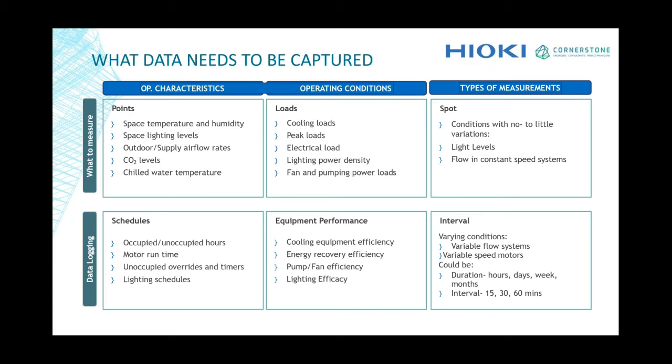When you come to data logging, you have things like when are the schedules of operation, whether it's occupied time, unoccupied times, what are the set points. If you look at motor runtime, how long does it run for, when does it start up, when does it stop, what is the load it's feeding. Unoccupied overrides and timers.